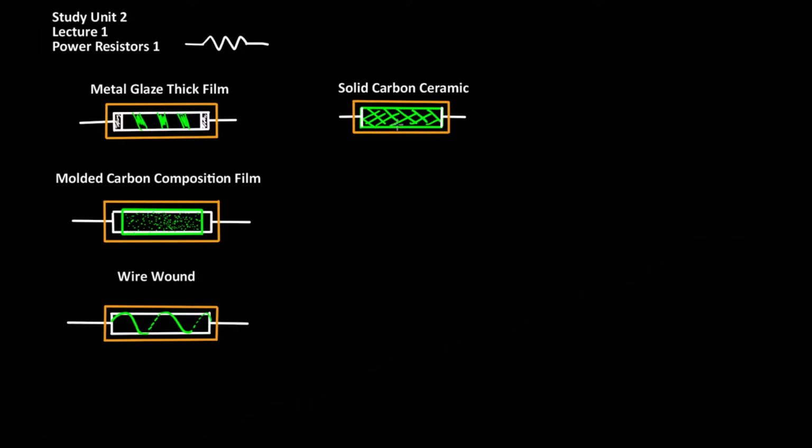This homogeneous construction gives it a high transient voltage, inherently low inductance, high thermal capacity, and of course finally mechanical robustness. The disadvantage of the solid carbon ceramic construction is that the devices are quite brittle, so any direct hard mechanical impacts will damage the device.